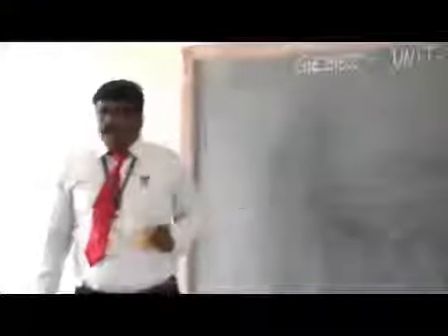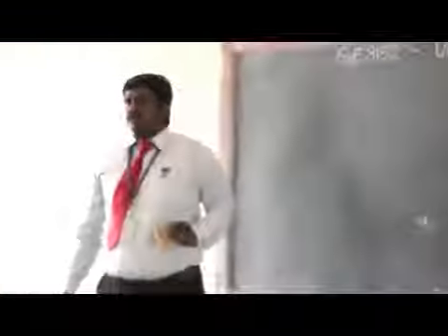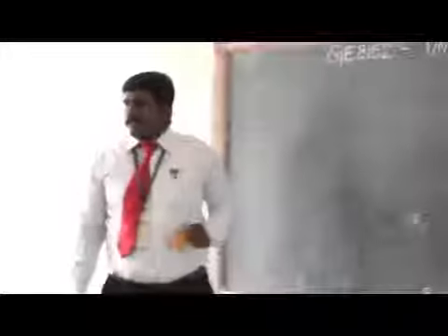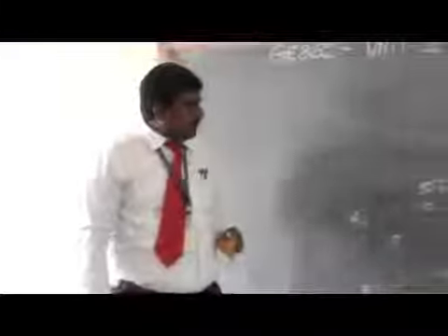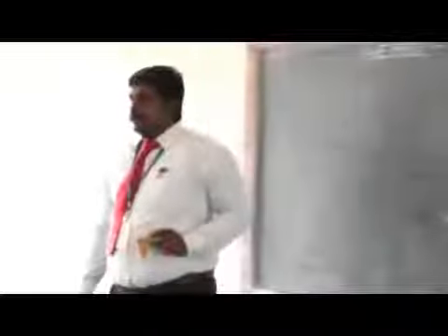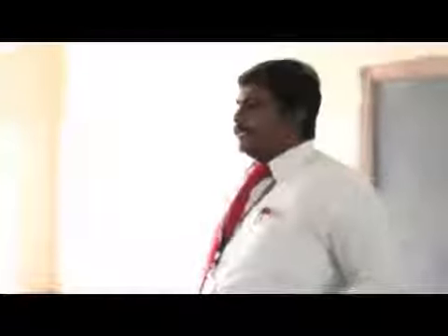Now we have to denote the corners. So let us say the base corners are A, B, C, D, and the apex. So we will just mark the top corner as O. So this is going to be your top view. So don't darken anything. So finally you can darken it. Now we have to draw the front view for this.